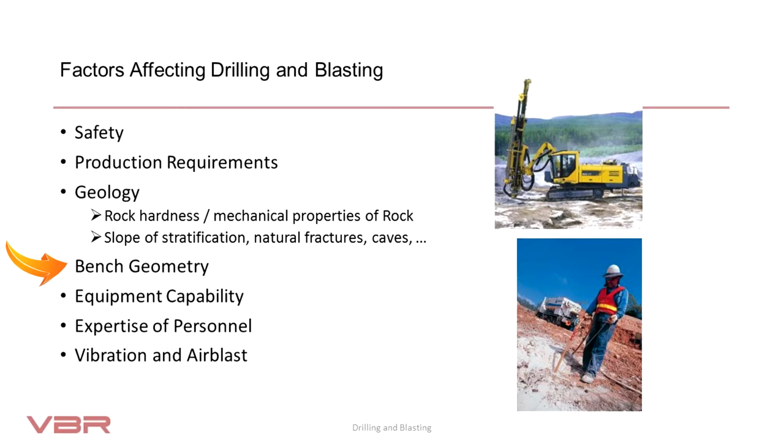The bench geometry, its width, height. The equipment capability: how deep can the drill rods reach? The expertise of your personnel on site. They may have limited knowledge and know only one or a few methods for designing the drill process. And finally, vibration and air blast. These are negative side effects of the blast procedure. We will deal with the topic later on in the video.